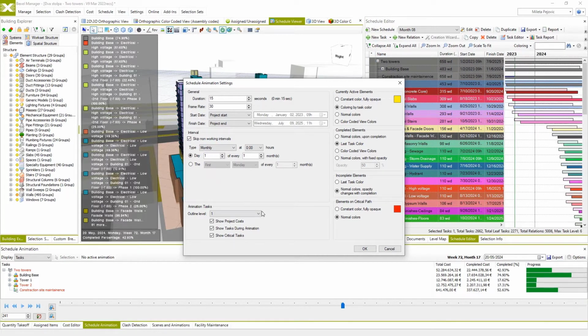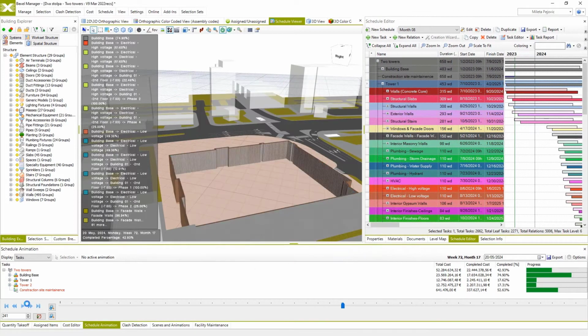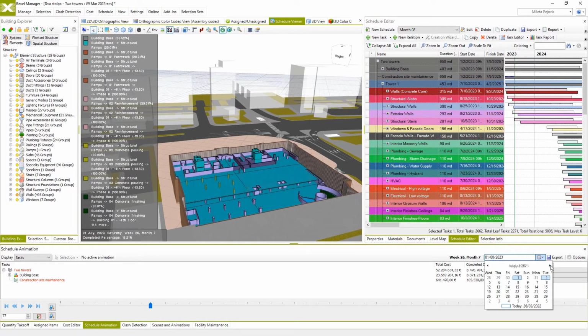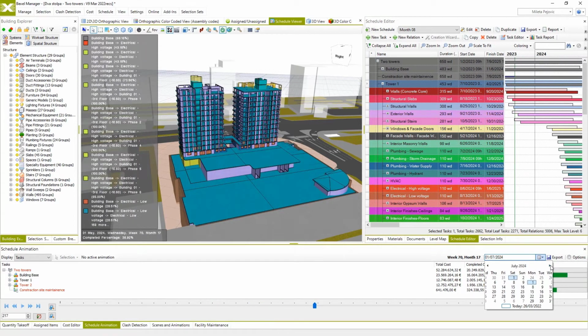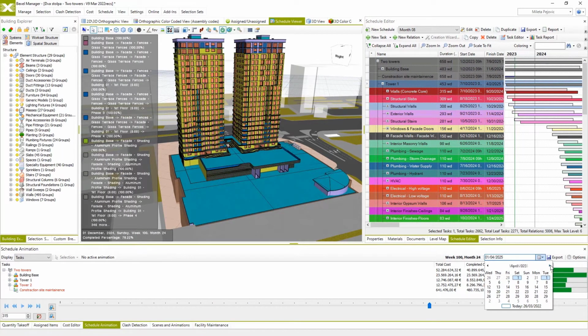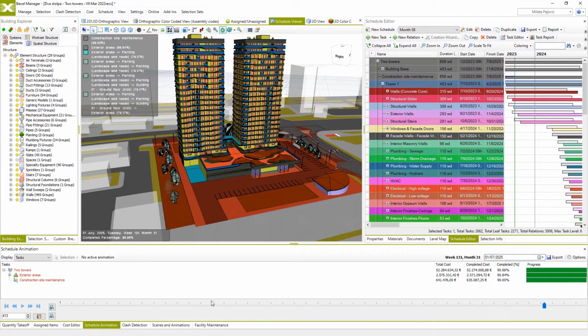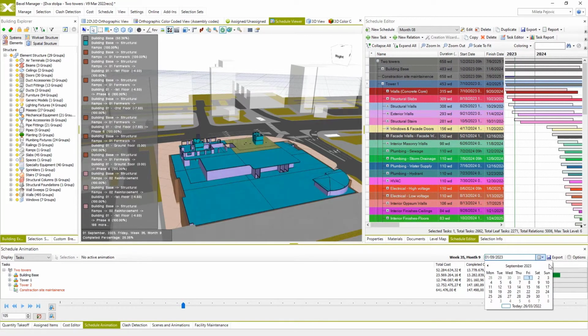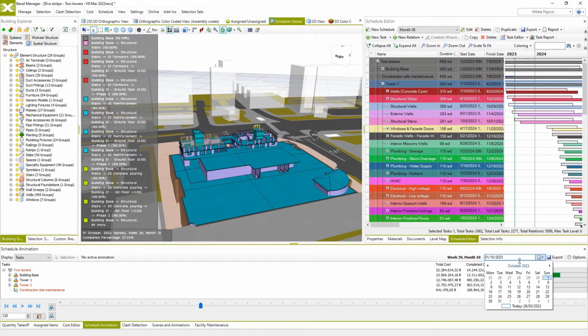So we can set a status date for our monthly progress certification and use available information from this virtually 5D BIM construction to help the on-site team. These works planned to be executed on selected date can be organized into selection sets of elements, or to be precise, BIM elements can be grouped into selection sets according to predefined look-ahead period.